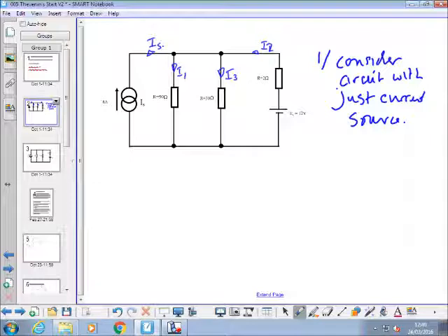Take it out, yeah, and short circuit it. Okay, so I'm going to put a line through it and a short circuit across there for this version of the circuit. We replace any source with its ideal internal resistance, and as you learnt last week, the ideal internal resistance of a voltage source is 0 ohms, and therefore we replace that source with a short circuit.